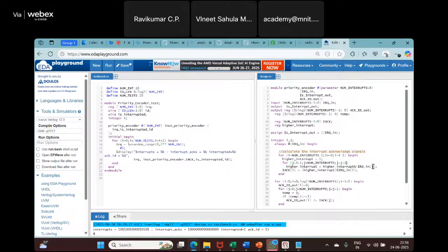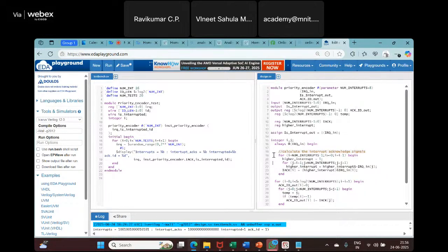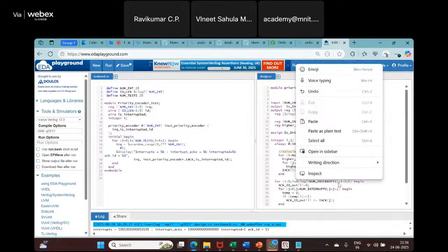So if any one of the IRQs is interrupting, then when I come out, if anybody above me is not interrupting me and I am interrupting, then that will be my acknowledgement. That clear? So this is to check the interrupt acknowledges.